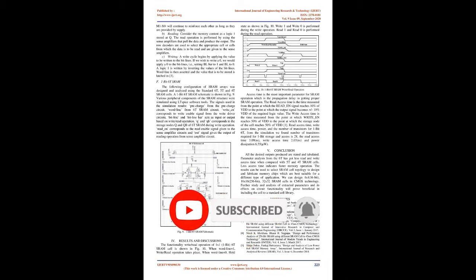1-bit 6T SRAM. The following configuration of SRAM arrays was designed and analyzed using the standard 6T, 5T, and 4T SRAM cells. A 1-bit 6T SRAM schematic is shown in Fig 9. Various peripheral components of the SRAM structure were simulated using LTSpice software tools.